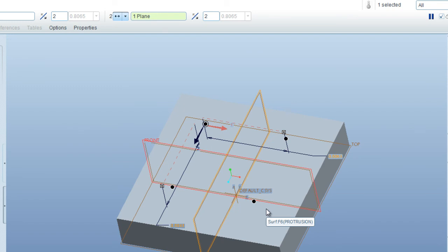So, for instance, if we wanted to use the LU relation further down the line, we could. If we wanted to go back to, let's say, the outline and change that to, say, 2LU, we couldn't, because the relation is only set up after this sketch, or after this feature is created. So there's kind of a scope of relations in that respect.